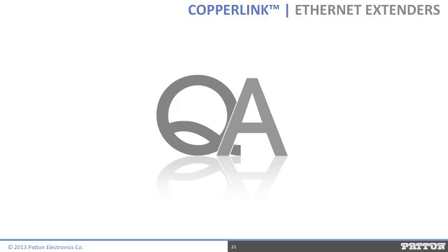Nathan, here's another one for you. What is IEEE 1588? IEEE 1588, Katie, is also known as the Precision Time Protocol. This protocol is used to synchronize clocks in a network that requires more precision than NTP or GPS, and therefore is suitable for measurement and control systems requiring clock accuracy in the sub-microsecond range. IEEE 1588 is often employed in protocols in the standard, as opposed to non-standard, Ethernet protocol stack. Non-standard Ethernet protocols use techniques such as time slot reservation.